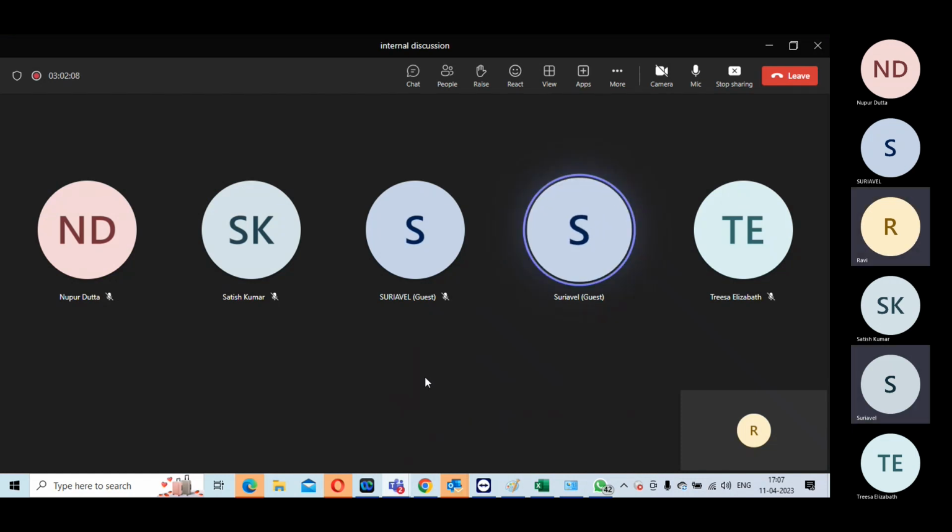Okay. Nice. See, let me talk about a few other options. You can definitely swap, you can definitely change the layer. He spoke about removing buffers and downsizing the cell. You should not downsize the cell on the critical path.